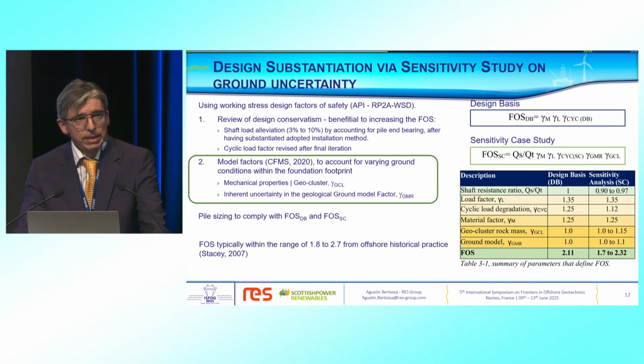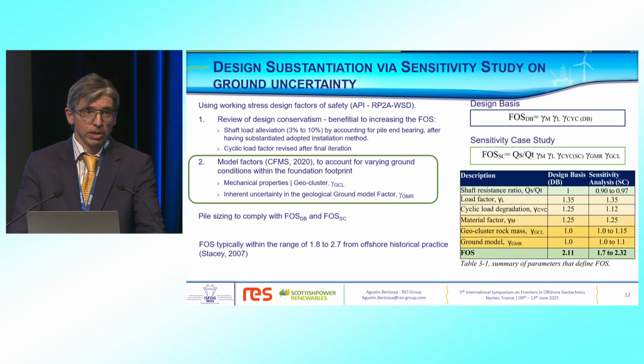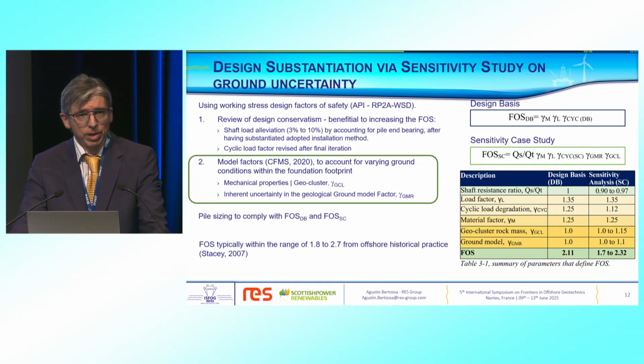So taking that site assessment, we carried out some sensitivity study to understand, well, if things go in a different direction during the installation, to what extent we can accept the design if we encounter that the ground is different to what we expected. So we used the working stress design factor of safety as a measuring parameter to correlate and understand the margins in the design.